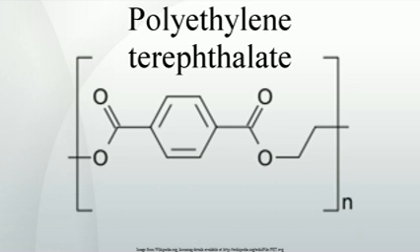About 60% crystallization is the upper limit for commercial products, with the exception of polyester fibers. Clear products can be produced by rapidly cooling molten polymer below Tg, the glass transition temperature, to form an amorphous solid. Like glass, amorphous PET forms when its molecules are not given enough time to arrange themselves in an orderly, crystalline fashion as the melt is cooled. At room temperature the molecules are frozen in place, but, if enough heat energy is put back into them by heating above Tg, they begin to move again, allowing crystals to nucleate and grow.